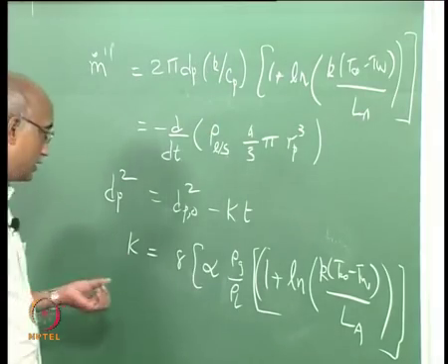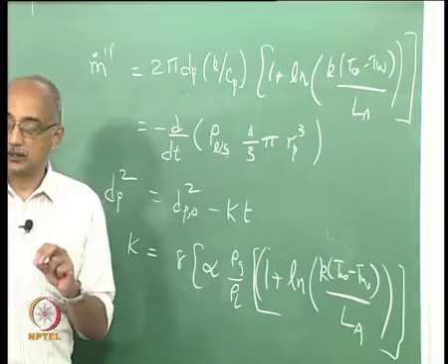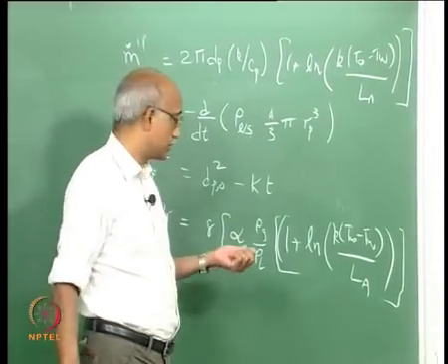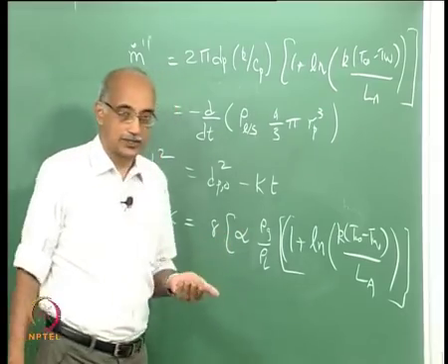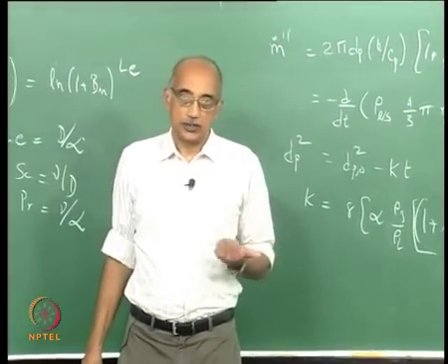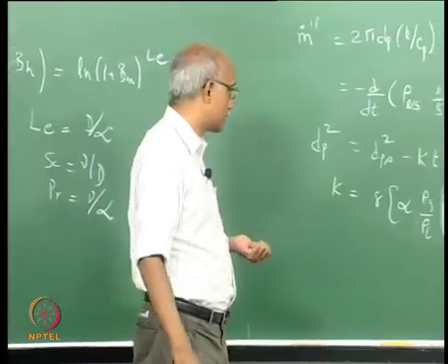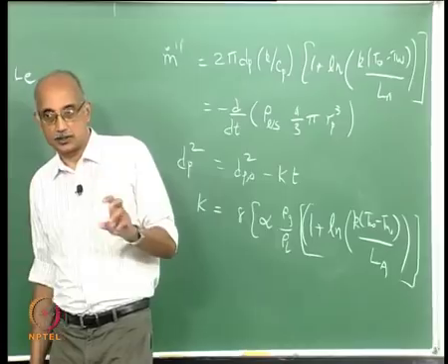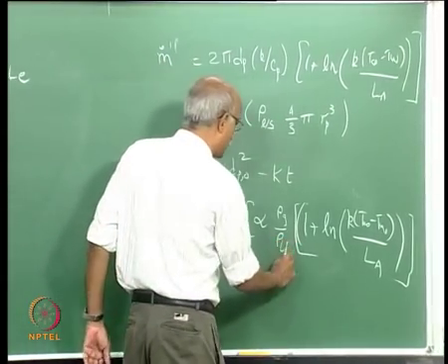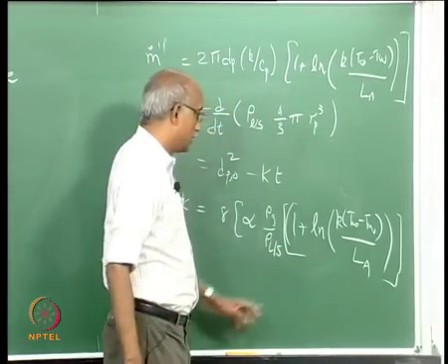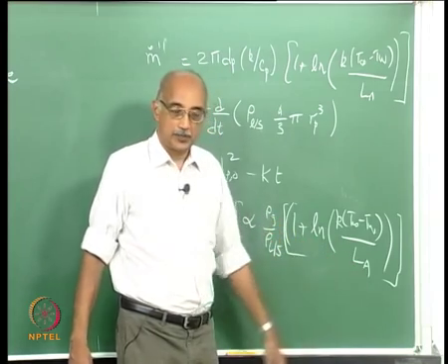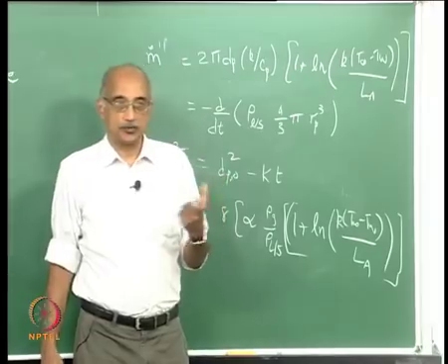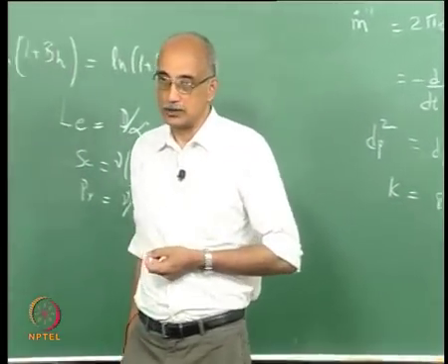And again, the key thing that you should remember, not necessarily the equation per se, are the dependencies, the terms that are involved. Alpha is the thermal diffusivity, which is equal to k by rho Cp. Rho g by rho L is the ratio of the densities of the gas and the liquid or droplet, or solid, and you have the latent heat of vaporization of the material in the denominator, k times the temperature differential T infinity minus Tw in the numerator.